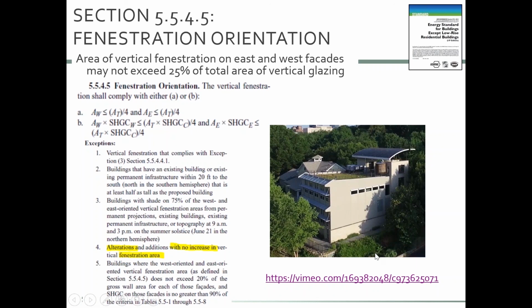So this is a picture of the edge of our building right here, and the south face is loaded up with glass. There's exterior shading devices as well as light shelves to help kick natural daylight deep into the space. And these windows are facing east, and you can see they're relatively small. They actually have external shading that looks like a Venetian blind. This particular one is also east facing. It's electrochromic glazing, so it changes its tint throughout the day based on a time clock.